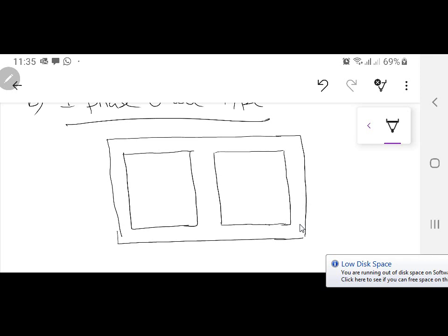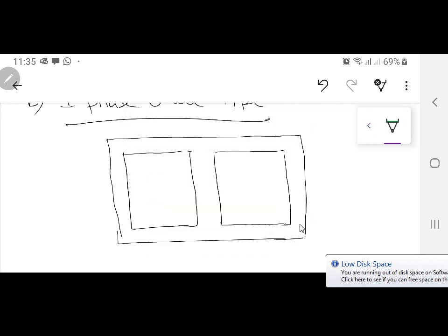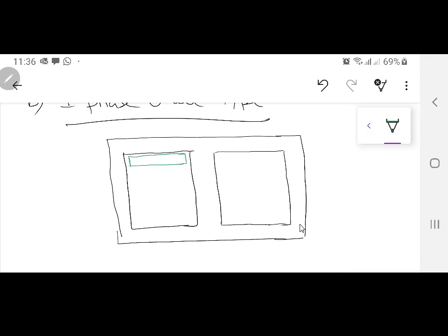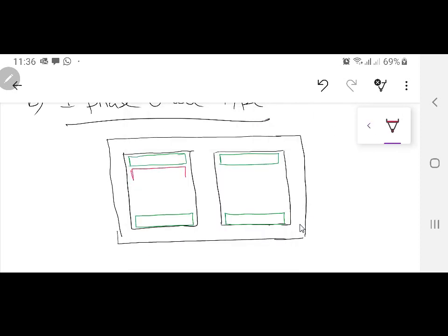Okay, so this is a shell type over here. Now, in the last lecture I told you that in a shell type transformer, you are first going to place the low voltage winding and then the high voltage winding just like this. Now there is another type of winding in the shell type transformer, in which first of all you are going to place the low voltage winding as close as possible to the T structure. Similarly here on this side, and similarly low voltage winding here, low voltage winding here. Then afterwards the next is the high voltage winding which you are going to place here.